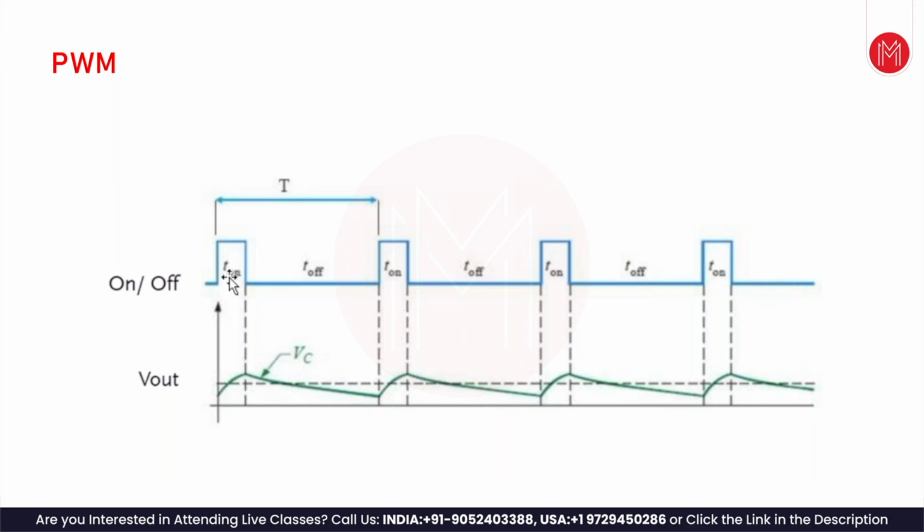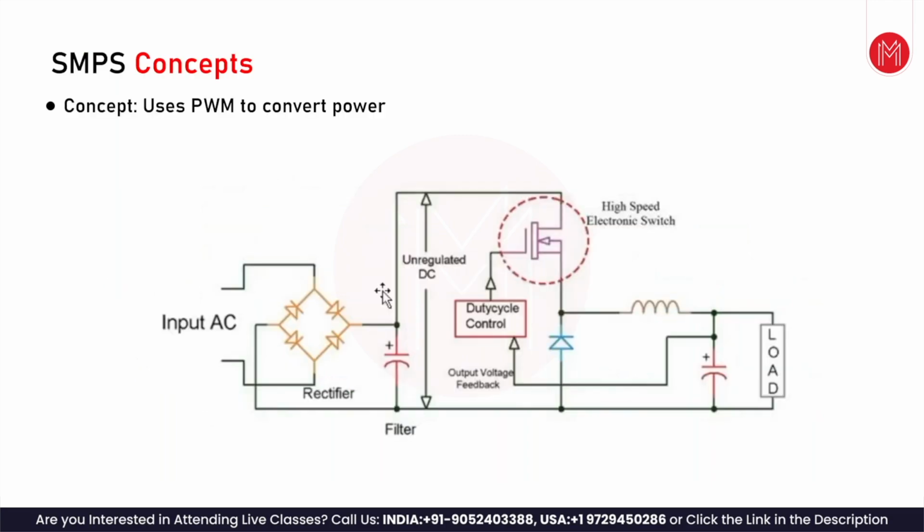Here, if you look at it, this is a high voltage unregulated DC. The voltage may be in terms of 200 volts or something. There is no transformer on the input side, which means it's not reducing anything. There is no transformer that reduces from primary voltage to secondary voltage. The high voltage itself is coming here, whatever the 230 volts or so.